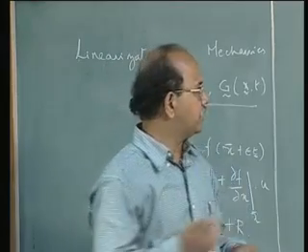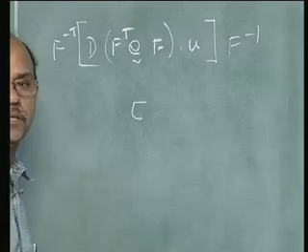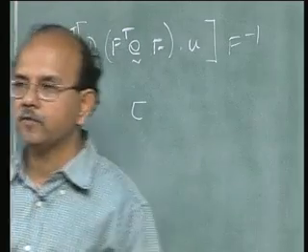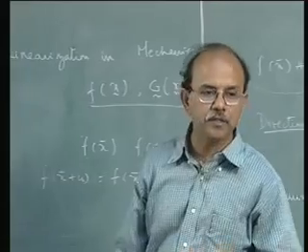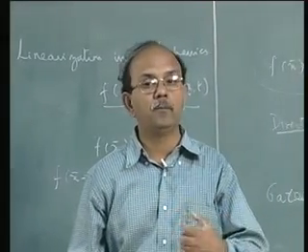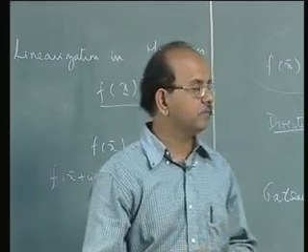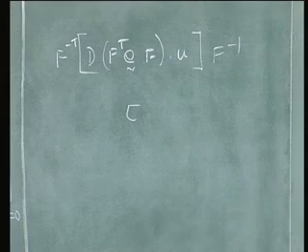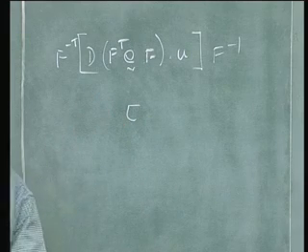So this is the directional derivative of a tensor like strain. Now please write this down: what would be the directional derivative of a quantity like Kirchhoff stress, which is referred to the current coordinate, and is defined as J into sigma? You do the same thing: a pullback operation, then calculate the directional derivative, and then do the push forward.